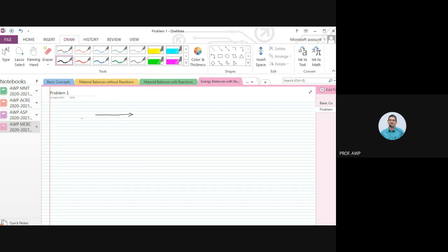After sulfur was burned, in the gas stream we had SO2, oxygen, and nitrogen. So let's say SO2 is 9%, oxygen is 9% in terms of mole percent, and nitrogen 82%. Okay. So this stream, let's say it is coming in at 1 atmosphere absolute pressure. Temperature is 300 degrees centigrade. After burning of sulfur, this goes into a catalytic reactor, a catalytic converter.